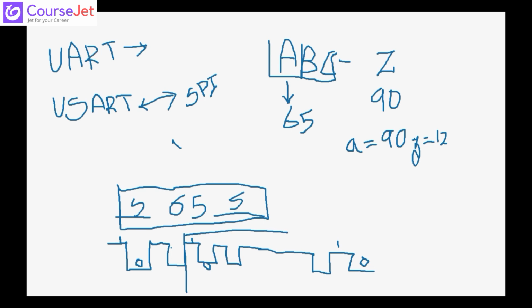It might be your start or stop. If you make a mistake and send a signal, it will still consider it as data only, and after 8 bits of data, whatever the next signal is, it will consider it the stop signal. Basically, in character-oriented data, you have a start bit, 8 bits of data, and a stop bit. So this is asynchronous, this is full duplex communication. This is UART, the universal asynchronous receiver transmitter, using full duplex communication and a data framing of start and stop bit.